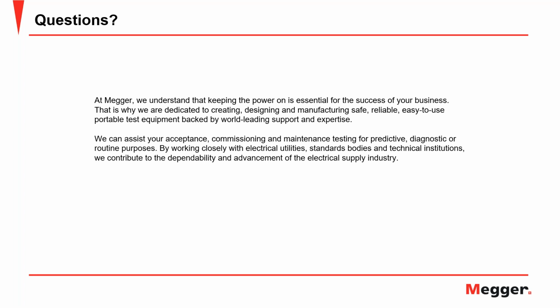All right, thank you. Ken, what is the normal capacity output current for the Delta 4000? So the Delta 4000 is capable of 100 milliamps continuous output. It can do 200 milliamps for 30 minutes and go up to 300 milliamps for 4 minutes. If you are measuring large capacitance specimens like cables or generators and motors, these will draw more current, and you can use what's called a resonating inductor to cancel out the extra capacitance and allow for testing.